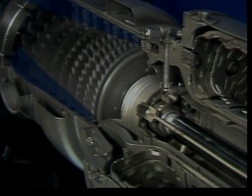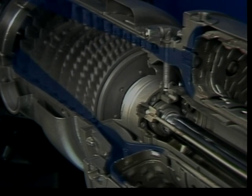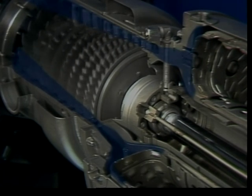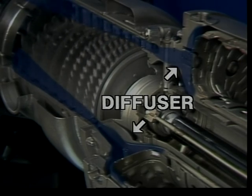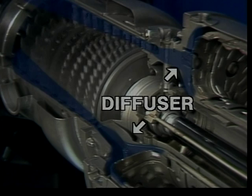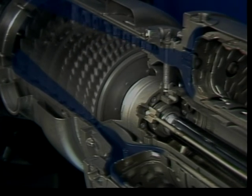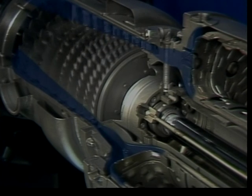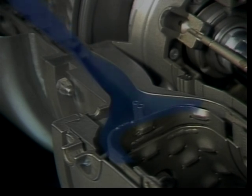After leaving the compressor, another pressure rise occurs before the air reaches the combustor. The pathway the air follows is shaped like a diffuser. The diffusion path increases in area and the air velocity slows down so combustion can occur. It is in this diffusion pathway that the final pressure increase occurs. At the rear of the diffuser, air pressure is at its highest level.